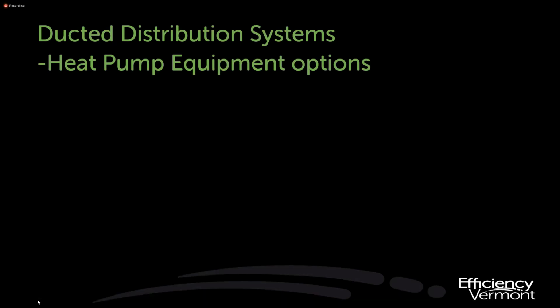So again, you can have a modulating boiler or furnace, but that modulating boiler or furnace is meant to work at its best efficiency when it's at the higher end of its spectrum of output. So if you're putting in equipment that's never going to really use its high end of BTU output, you're never going to get the true rated performance of what you're buying or what you're putting into the building.